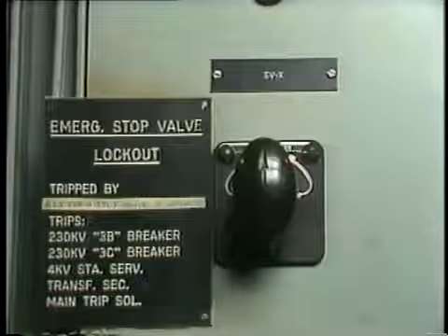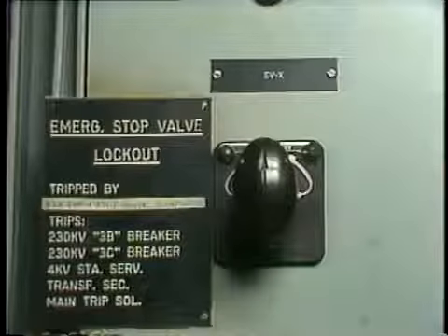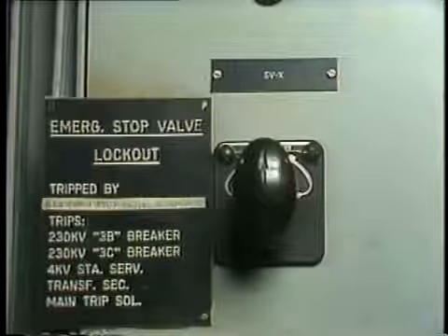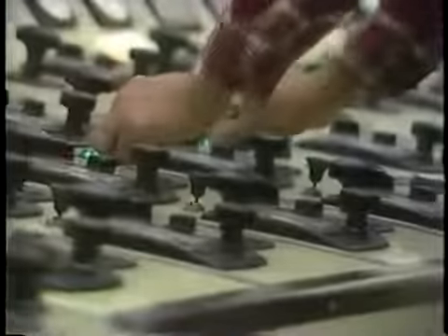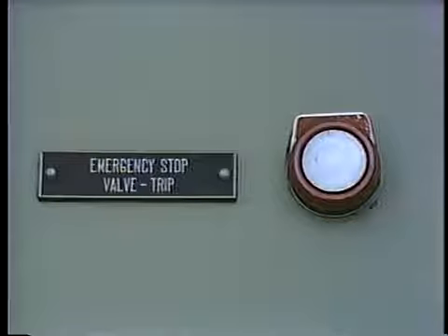On rare occasions, the operator may lose both FD or ID fans. When this happens, the operator has little or no control over the flow of air and gas through the boiler. In this situation, the boiler cannot continue to operate. Most boilers have interlock systems that will automatically cut off fuel flow to the boiler and extinguish the boiler flame if both FD or ID fans are lost. If this is the case, the operator must immediately follow plant procedures for purging the boiler of all combustibles. If a fan cannot be returned to normal operation quickly, then the operator may also have to trip the turbine.